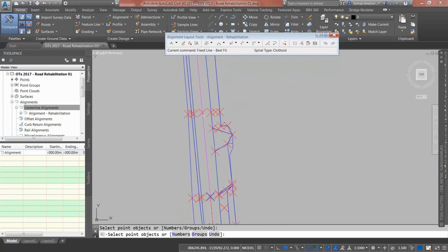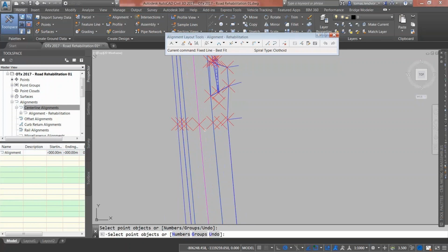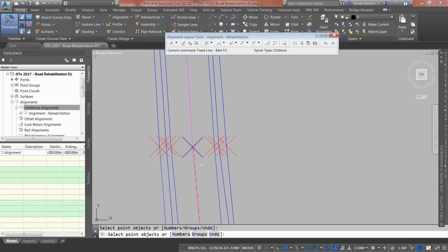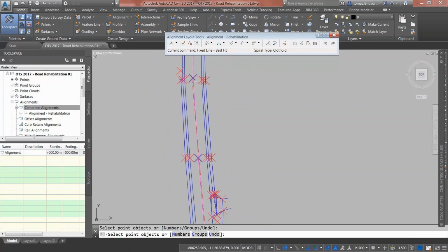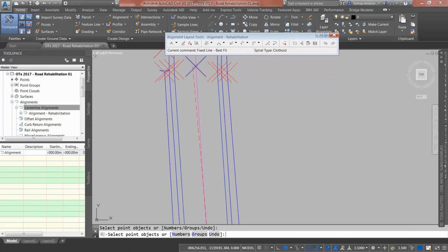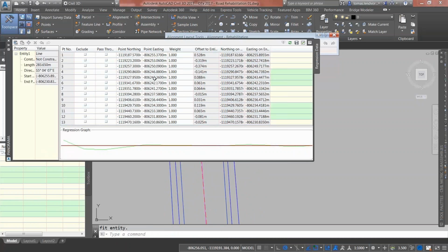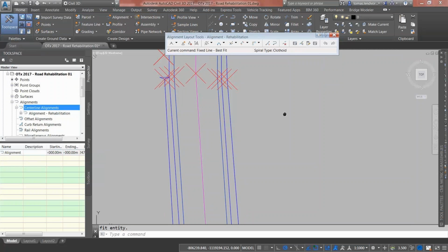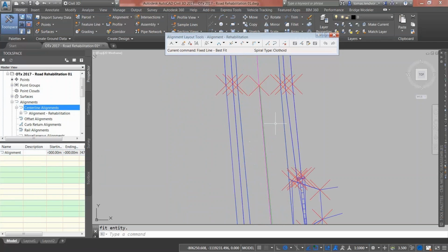And as you saw, I can pick up points, I can pick polylines, I can pick lines, whatever is available and whatever we can do. So, with that, I'm just picking points, and because I'm defining lines, I can see, okay, maybe this last point is too much. Because I have an offset, which you see is too much, 80 centimeters, just forget about this, so I want to exclude this point. So basically I just picked this point, but finally I realized, okay, I don't need it.